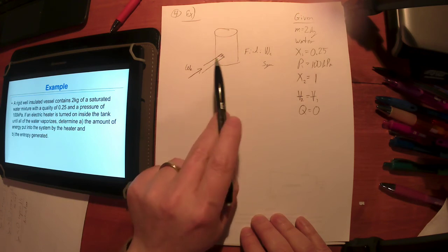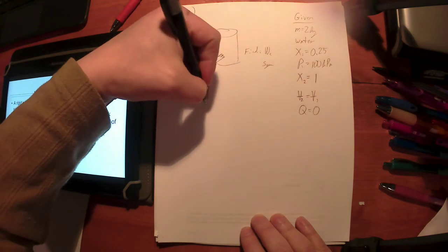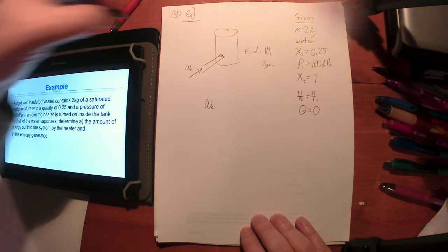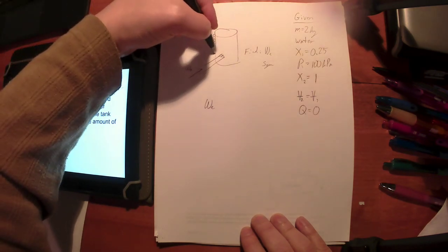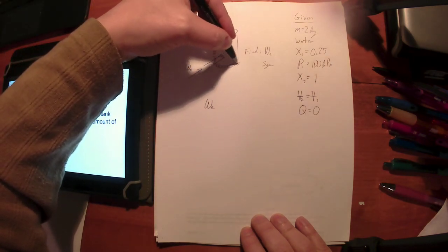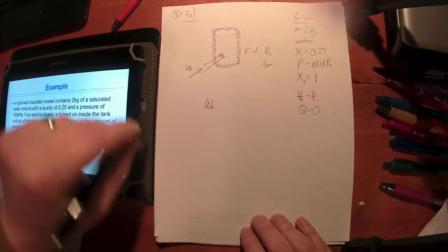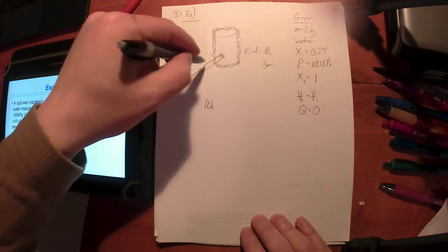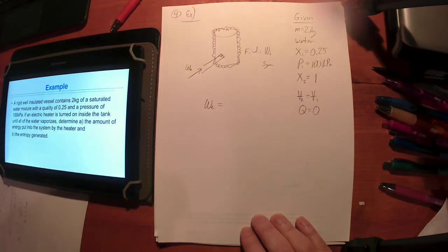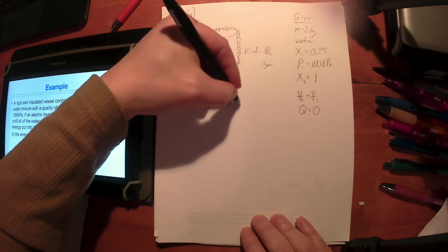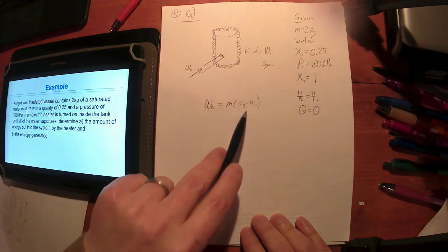Now, I asked earlier, what tool are we going to use to find this work term, this energy term? The gut reflex at this point should be, that's a first law equation. So, first law says add the ins, subtract the outs, and again, this is an insulated tank, so if you like, draw some kind of insulation on there. All right, my awesome drawing skills there. So the only thing crossing the boundary is this electrical energy coming in, so that's going to be the entire left-hand side. It's a closed system, so in minus out equals change. The only thing changing here is the internal energy.